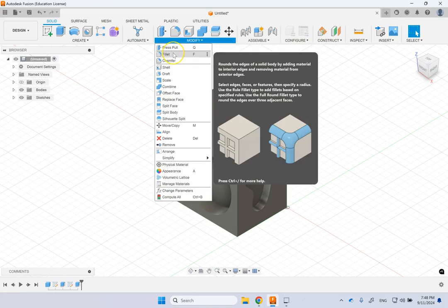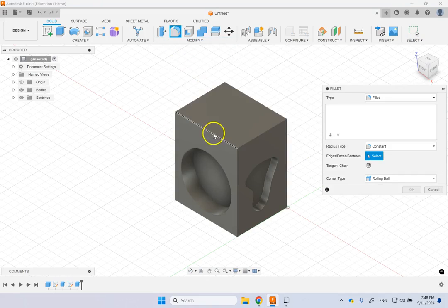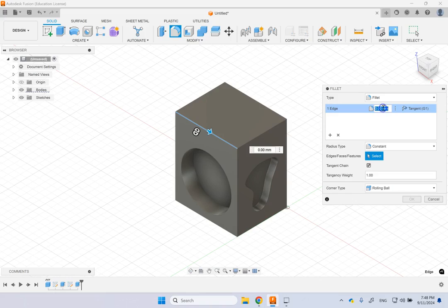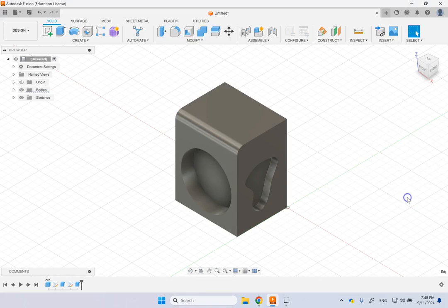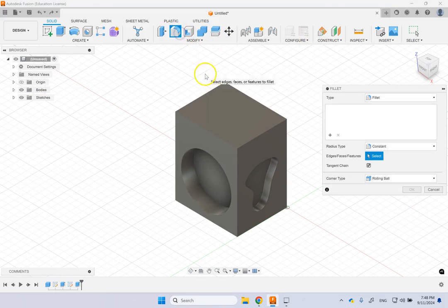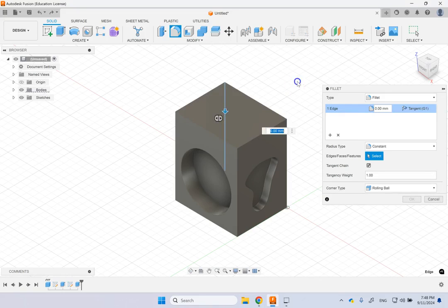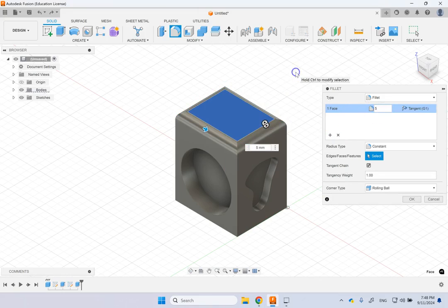The next command you can do is a fillet, which is rounding an edge so it's not sharp to cut your skin, or if it's an internal edge, you want to remove a stress concentration. So here you click on fillet and you pick an edge and you provide the fillet radius, and there we go. Here, that's filleted. Now you might say, what happens if instead of an edge you pick an entire surface? Could you do that, right? Can I pick an entire surface and provide 5 mil? Yes,